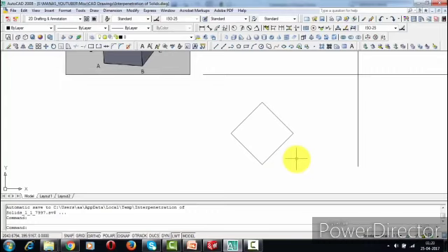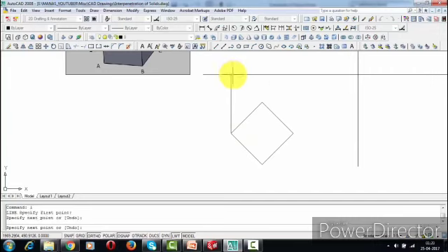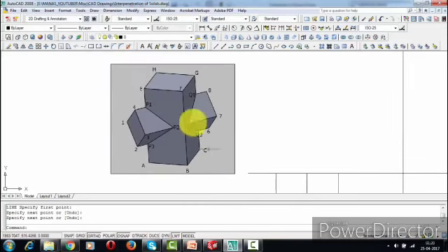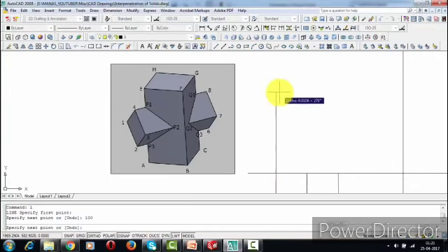All right, now we're going to look at this from the front, and for that I'm going to be projecting these lines from the bottom like this. Now this vertical prism in fact is having a height of, we are assuming that height to be equal to 100 millimeters. So what I'm going to be doing is I'm going to go 100 millimeters above, something like this, and that's it.